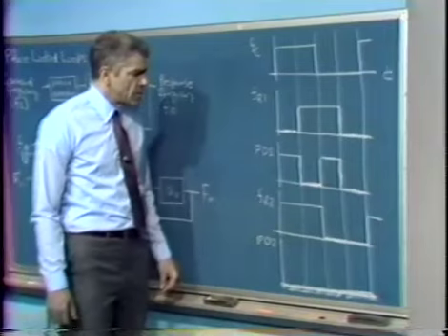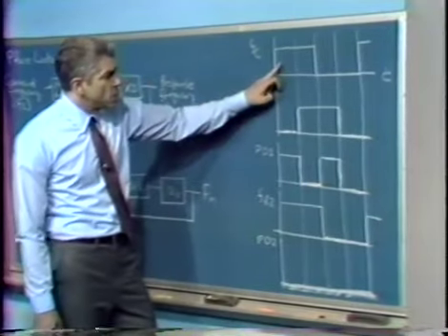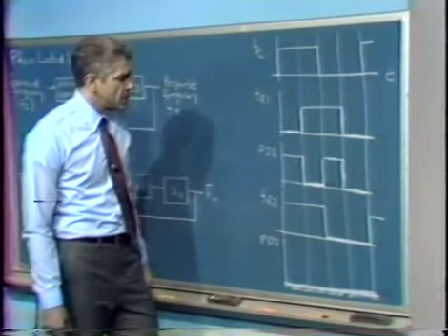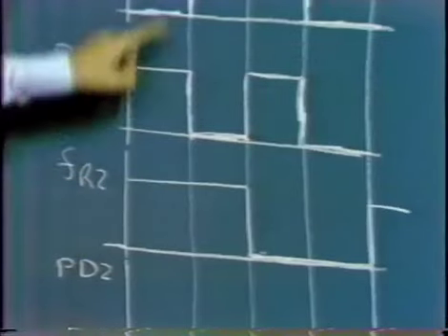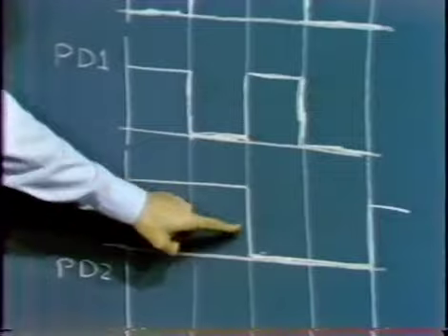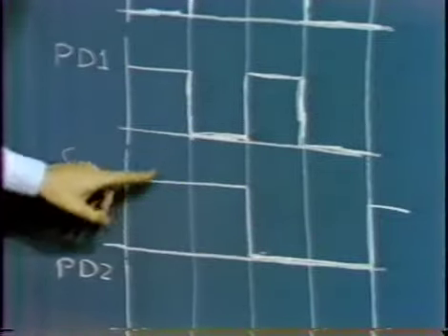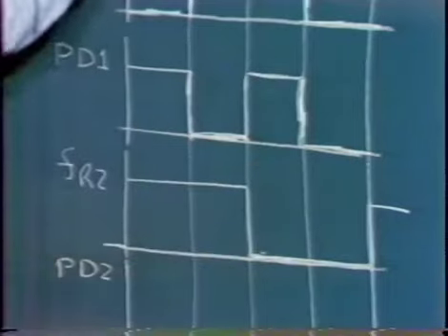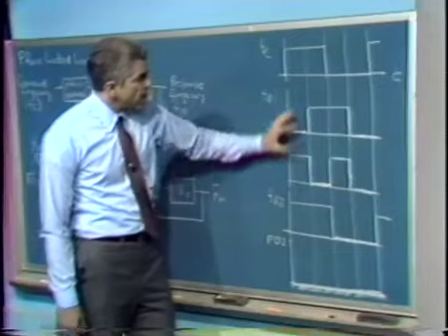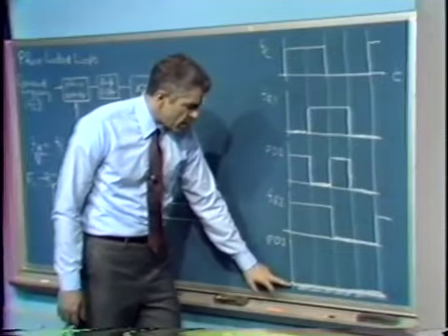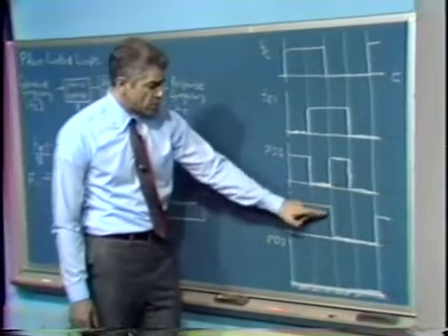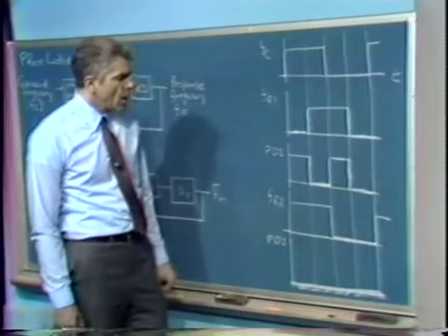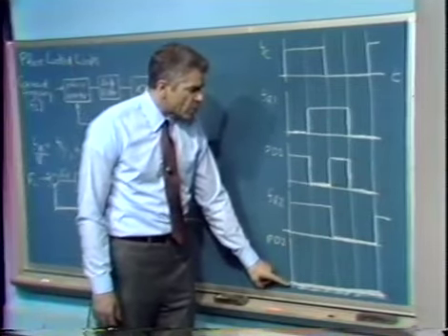indication. Let's consider what happens if the relative phase between the input and the output signals change, such that now the response of the system, the second response of the system, is in fact in phase with the command signal. So we have one that's directly in phase with the command signal. In that case, the output of our exclusive OR gate is always low. So this would be the output from the exclusive OR gate that corresponds to this second response from the system. If we average that, of course, we'd get 0.